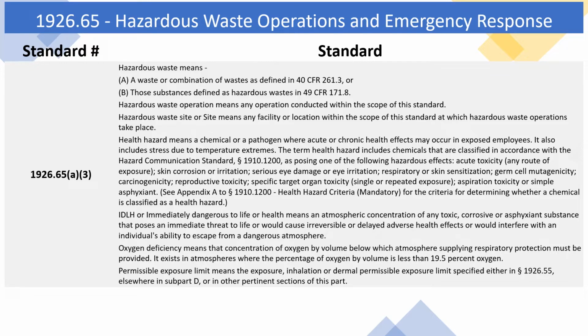IDLH, or immediately dangerous to life or health, means an atmospheric concentration of any toxic, corrosive, or asphyxiant substance that poses an immediate threat to life or would cause irreversible or delayed adverse health effects or would interfere with an individual's ability to escape from a dangerous atmosphere. Oxygen deficiency means that concentration of oxygen by volume below which atmosphere supplying respiratory protection must be provided. It exists in atmospheres where the percentage of oxygen by volume is less than 19.5% oxygen.